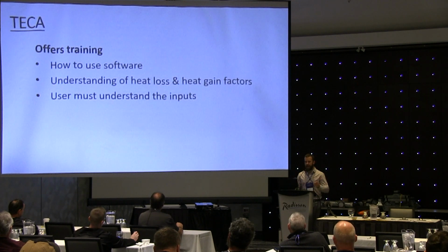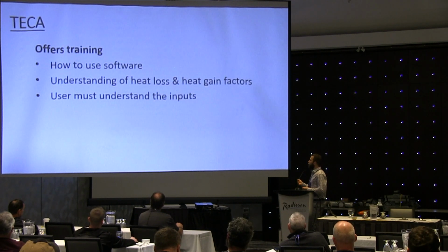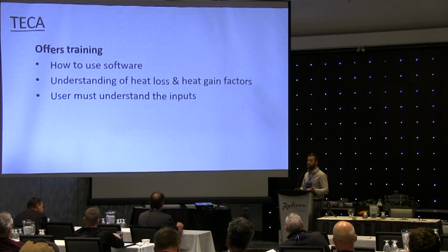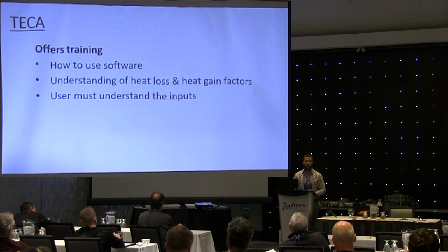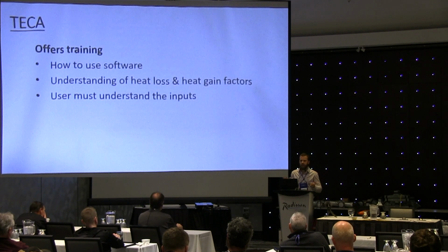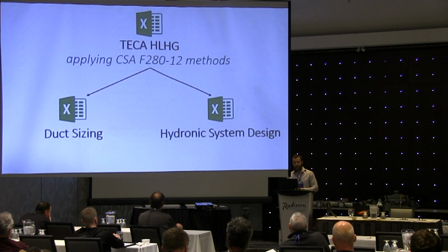So yeah, back to TECA. What we do is we developed this software to do the calculation. We offer training for how to use this software, and to understand the inputs that are going into it. That's a big part of it. 2 people can sit down at a set of plans and do a heat loss for it and probably get different results. When I do a course with people, sometimes 15 people will have maybe a couple that have the same results, and it's because little things get missed, little like skylight shaft walls get missed here and there. So understanding the inputs is huge.